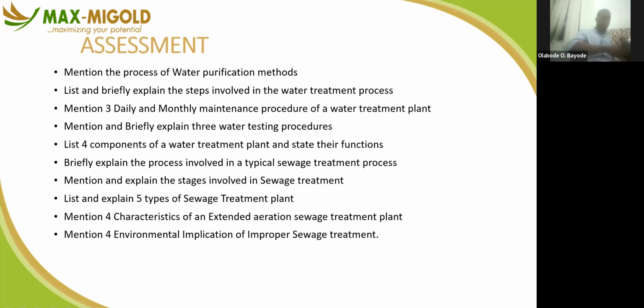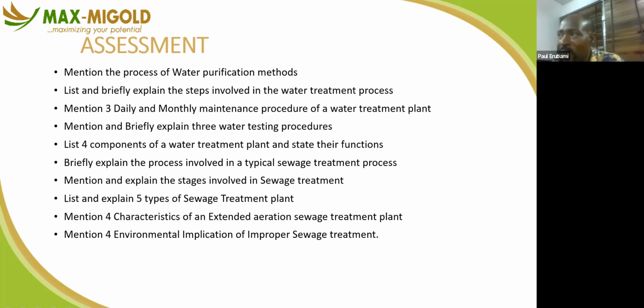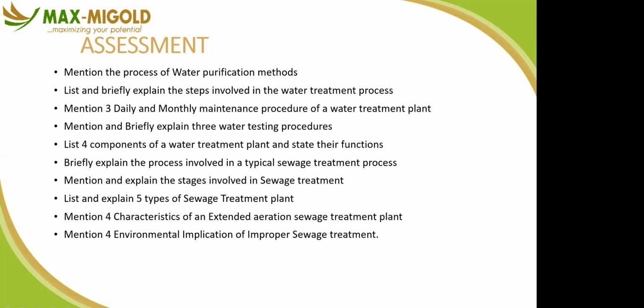There is nothing you can do. The only thing you can do is bring your tank to the floor level and use what we call a pressure pump. Install a pumping machine and put a pressure switch on it. It will take the water to every floor and you have the same pressure all through. All through? Oh, yes. Okay.